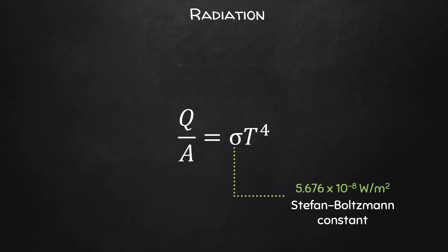One thing that you should always keep in mind is that the Stefan-Boltzmann constant is very, very small. But also that the temperature here in this case is to the power of 4. So these are two juxtaposed quantities. One is very small and one will tend to be very large. So therefore, unless the temperature is high enough, radiation would not typically be considerable compared to the other mechanisms in question. Okay, and you should really try to get a feel for when radiation is negligible and when it becomes something that is considerable.